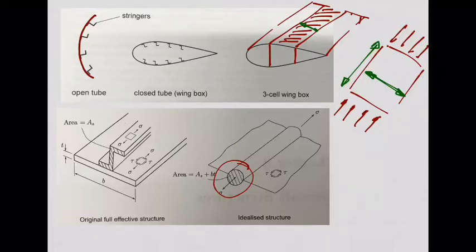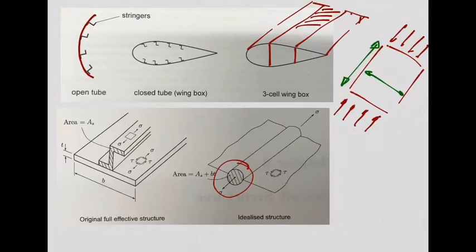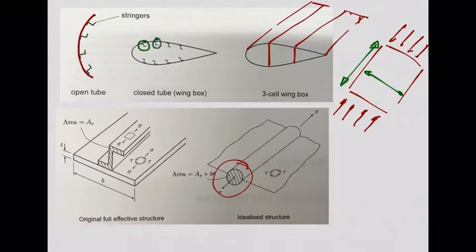But sometimes this is not enough. We need something more, because even that way the buckling can happen. You see these stiffeners here, we call stringers. We need also, for example, a stiffener here. This stiffener will also run in the longitudinal direction, so I am reducing even more this dimension of the plate so that it does not buckle. You see what I mean?